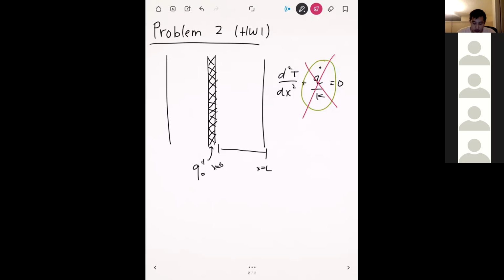You're not going to have thermal generation, because all the thermal generation is localized to just one location. The only place where heat is being generated is at the heater. Inside the slabs of material, no heat is being generated, and that's where I wanted you to solve for the temperature distribution. To sum this up, the only time you should include q dot is when there's heat being generated within the actual solid.